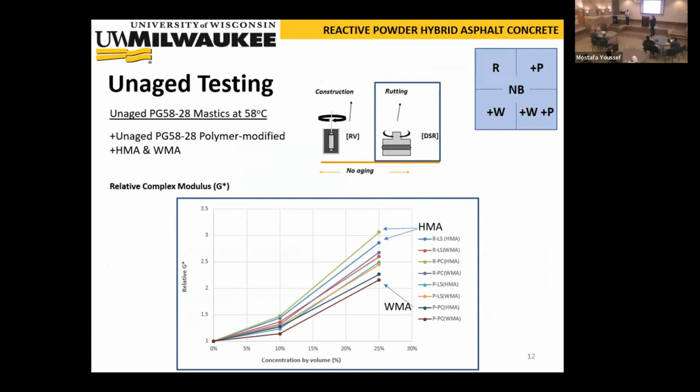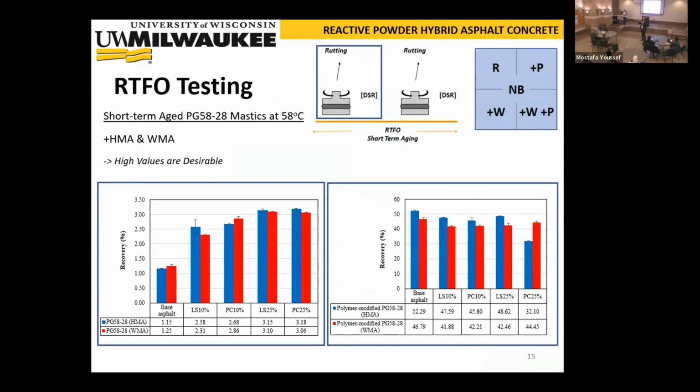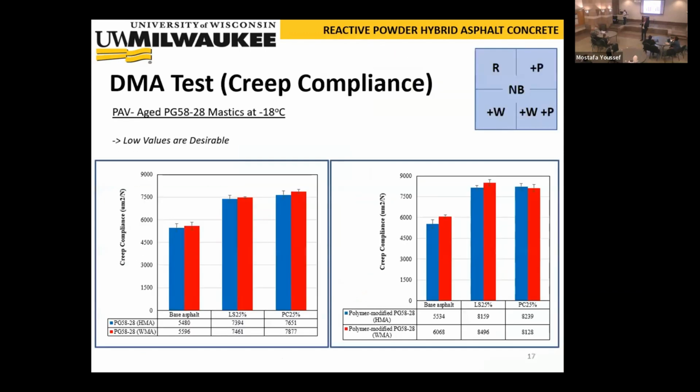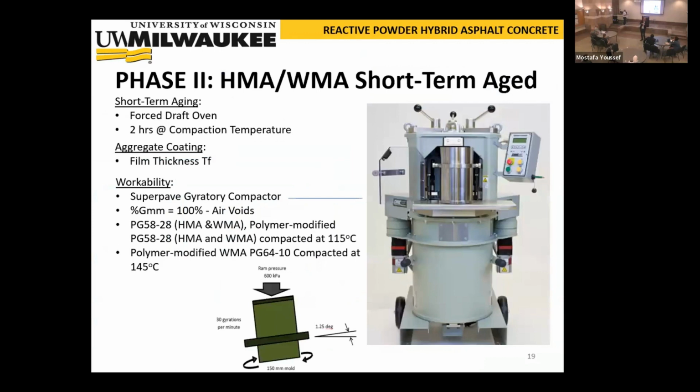Now I understand that the binding with the asphalt for us typically will be very strong, because at that kind of temperature you remove OH groups from the cement side, and that will bond chemically with asphalt. Now, because I tell you that what we did with Ferrovial, we did some samples like that and crushed them. I was expecting the asphalt not to bind to the cement grains. So we got a black and white image, everything would be asphalt on one side, grains on the other.